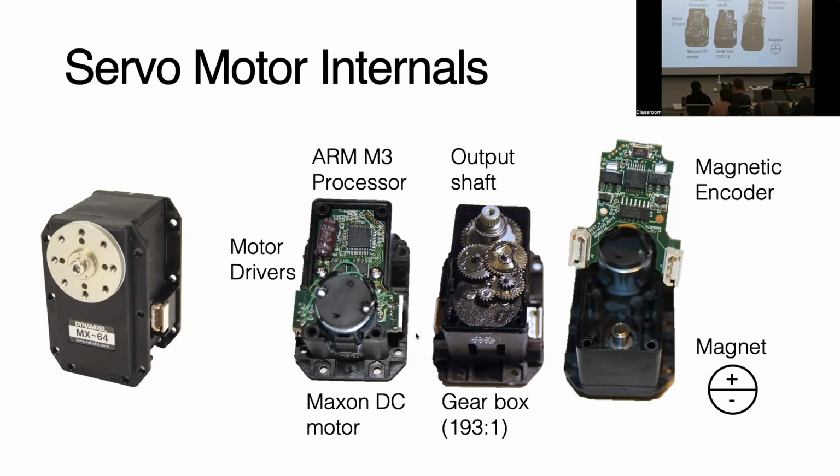All right. And then to run the controller, there's a microprocessor here that is running that control loop, taking in the feedback from the sensor that's reading the position of this magnet and driving the motor. And there's a motor driver here and two big MOSFETs that are sending current through that motor to drive it to one position or the other.